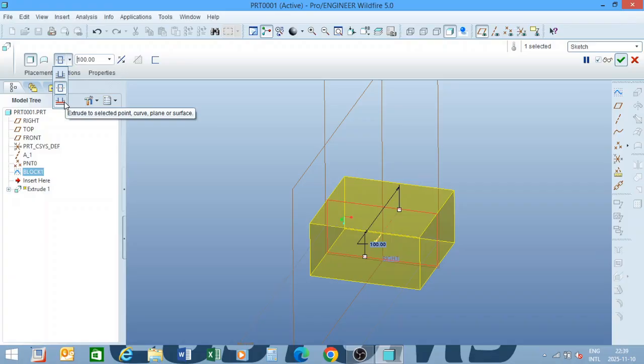So in the videos moving forward, you'll see if we do an extrusion on, say, a tube from one side to the other side, or any assembly or any part where you have a limit that you need that thing to go to, it makes your life a lot simpler. Instead of dragging it, measuring it, trying to get it to the same surface as other parts, you click on the blind function and you click on that surface and it will line it up on the same level. So this just makes your life a little bit easier.